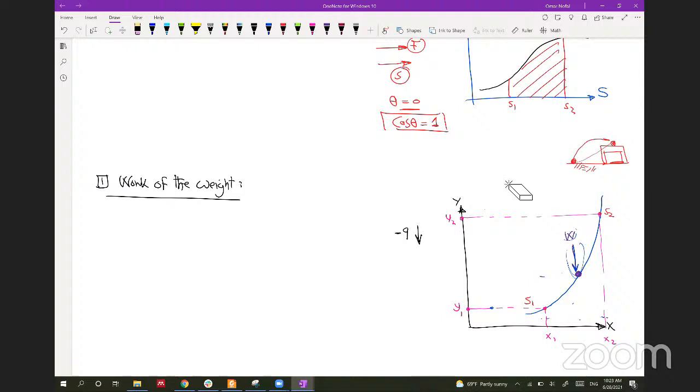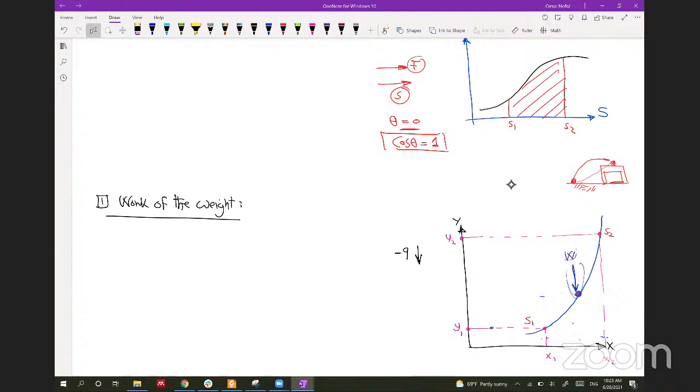All right, so let's get the weight force. We have the weight vector equal to negative W, the weight of this body, in the direction of j hat, in the negative direction. So we have the weight as a magnitude, and the direction is going down. We know that the unit vector here is j hat, and the unit vector here is i hat. So how about the dr?